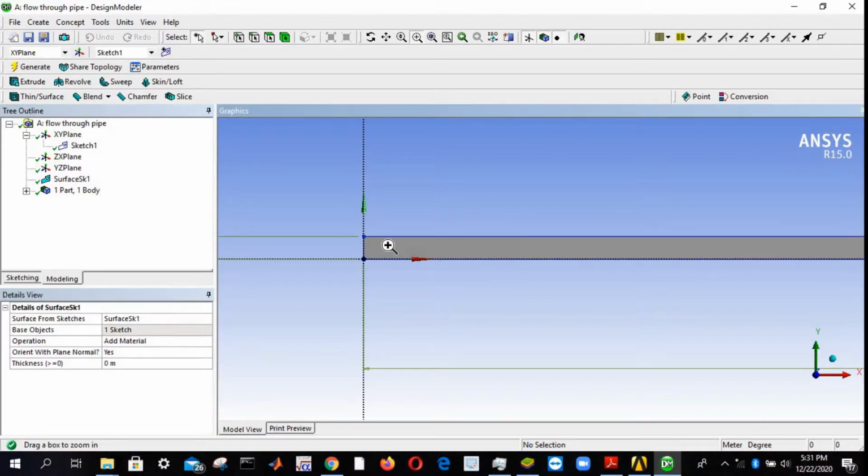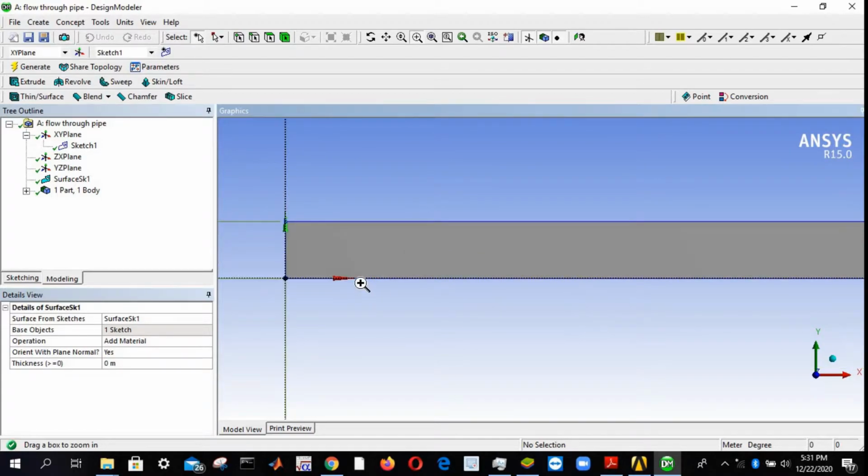Ansys Fluent provides a specific feature in which you have to analyze this rectangular portion only, and by just clicking on the axisymmetric model you can analyze the whole flow through circular pipe. So for now our computational domain will be this rectangular portion only.